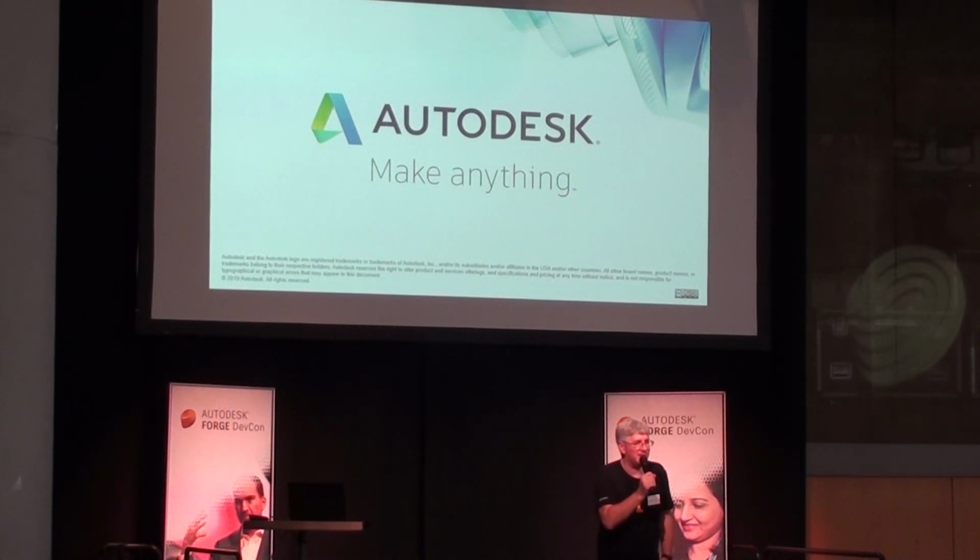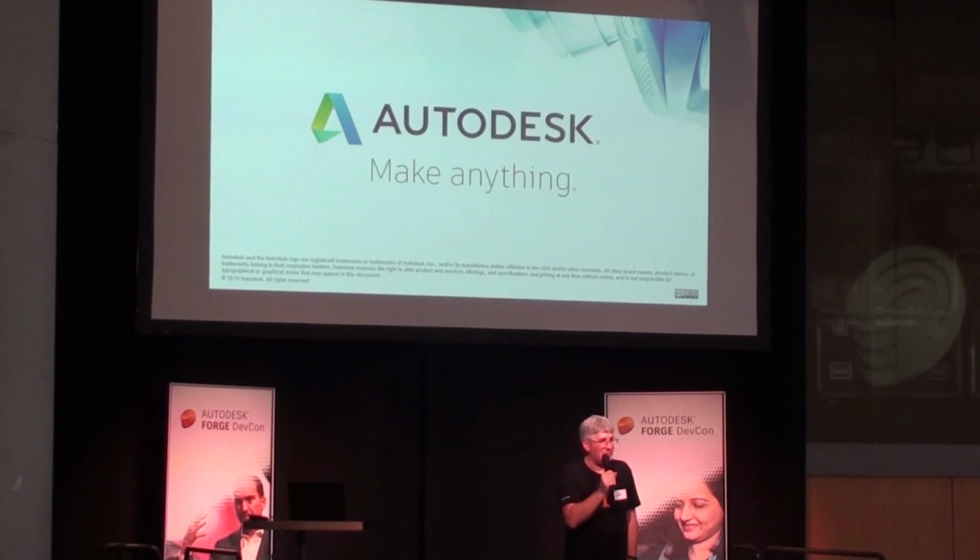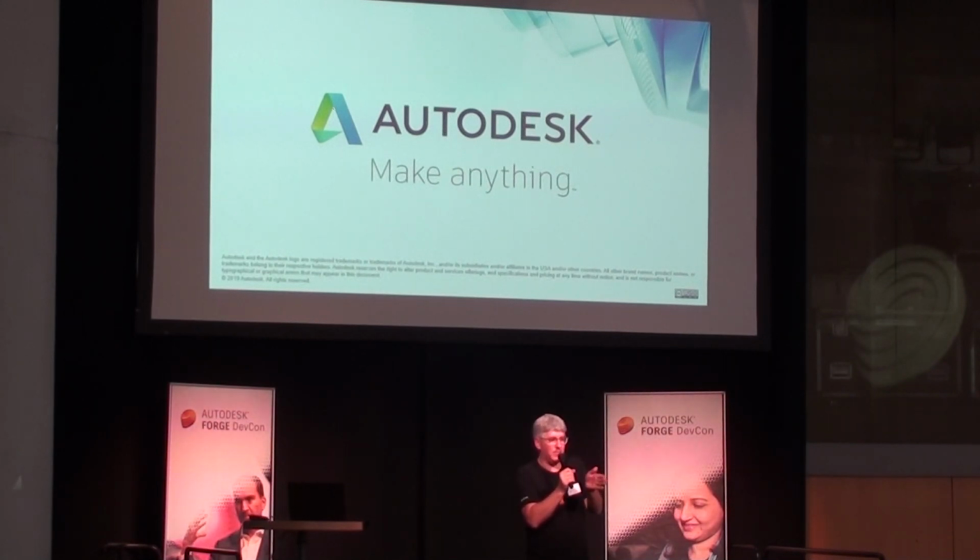What happens if you upload an assembly with an unresolved file, right? Well, it won't get stuck, but you probably aren't going to end up with the right assembly out the other side. Since we don't have dialogues, if you've done a skip, we'll load the file, but you're probably going to be unhappy. So, when you do the local debugging, we actually have an input file folder. The best way to do that is bring everything into that folder and make sure that your project isn't referencing something that isn't in that folder. We've had people work through that, and that tends to work pretty well.